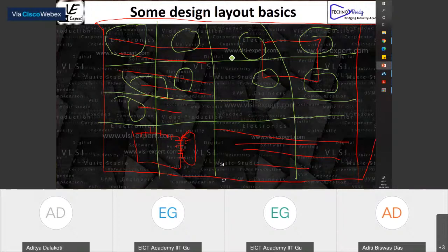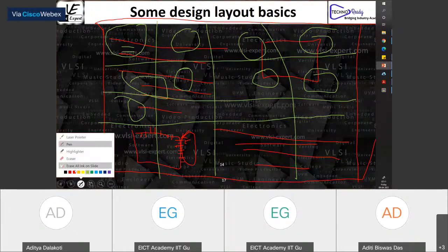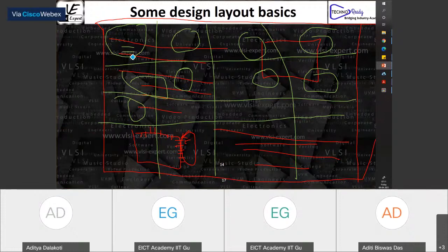Once it does that approximation, the tool is then able to figure out: now that I've done that approximation, do I have all the available resources or not? If it doesn't have available resources, then it will error out at that point. If it has the available resources, it will start creating those tracks. Till now, no tracks have been created. It is just doing approximation. Then it will start creating those wires, putting those connections in place. It will do vertical and horizontal connections to wherever they have to go, and between different regions as well.